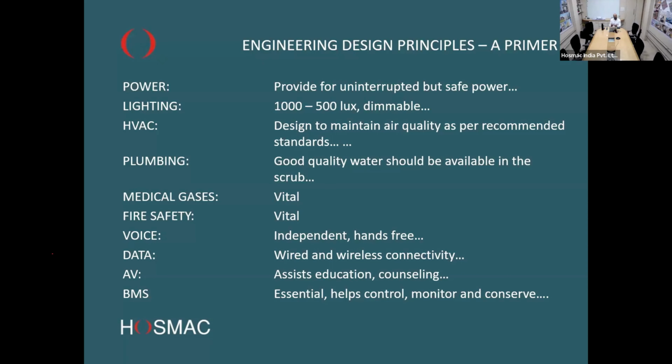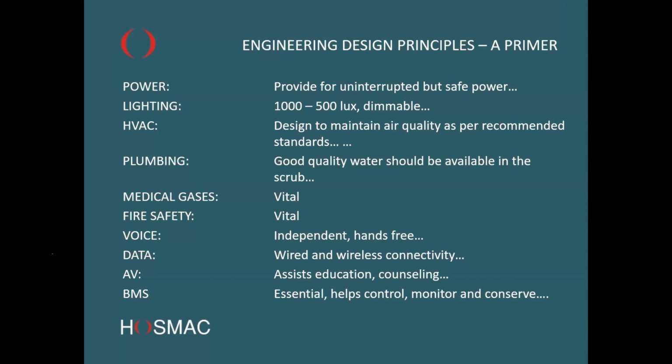So when you're working under very bright lights and you need to step out and look outwards, you would feel blinded, which is why the peripheral lighting in the operating room has to be scalable up to 1000. Normally, you would maintain it at maybe 200, 250 as is convenient, but should the surgeon need to, you should be able to scale it up to 1000. This is the requirement as per standards.